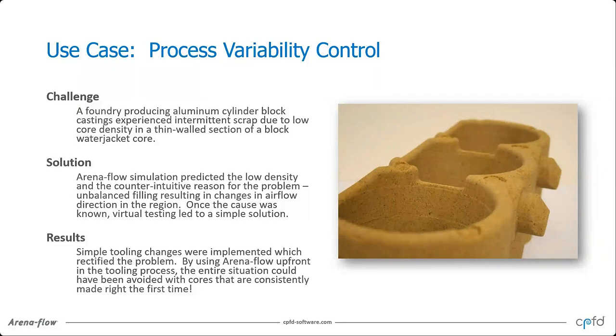And what happened is one side filled up faster, and when it did, there was a pressure change due to the blow tubes being filled, and all of a sudden you had this imbalance where sand that was flowing one way through the webbing turned and flowed a different way. And if that was not locked in, tightly compacted, it didn't move. And you'd start to see, right in that webbing, things opening up where you could see through it at times.